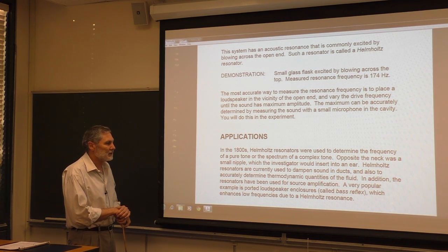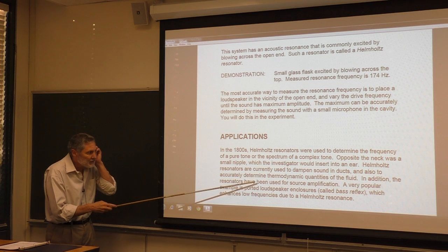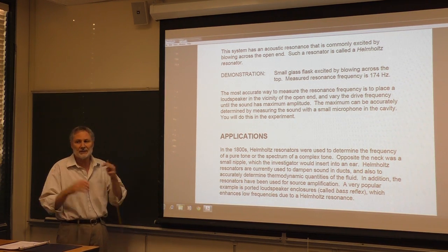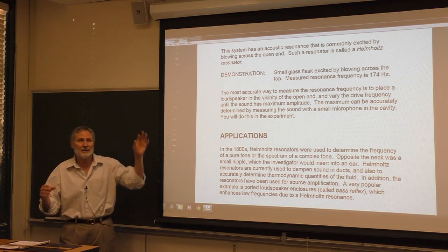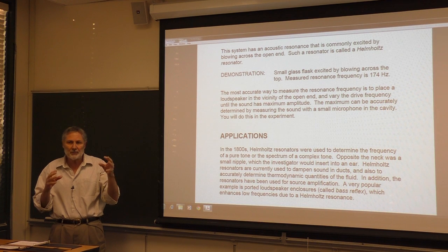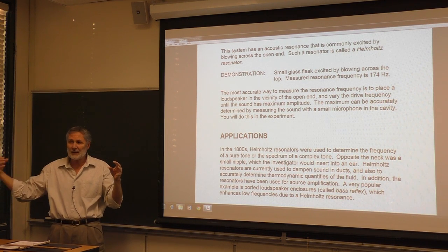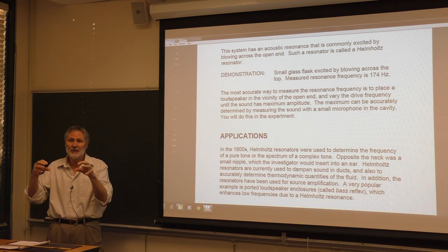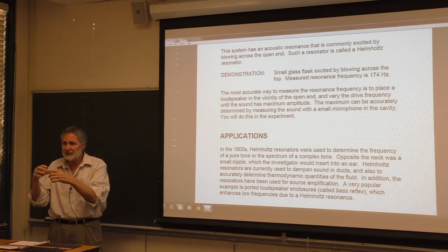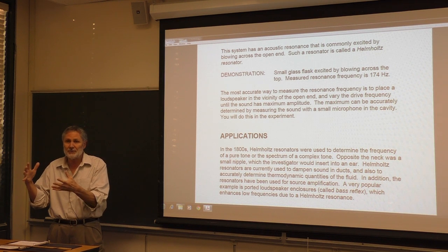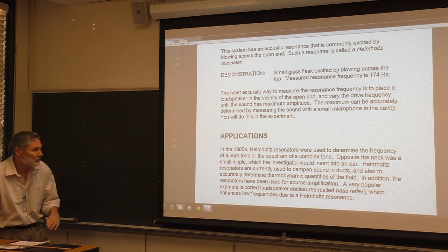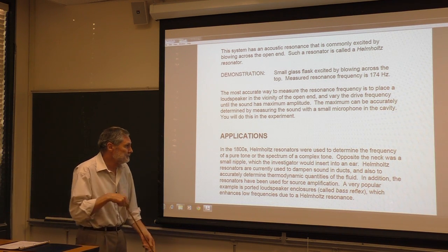They have a lot of current usage, as I'll explain to you right now. They're commonly used in ducts. If you've got unwanted sound, some kind of air conditioning or heating duct, and it's roughly a pure tone, you can tack on a Helmholtz resonator in the duct there and tune it to be approximately that frequency. And because of the resonance, it'll resonate. That energy has to come from somewhere. It comes from the sound wave. So you can dampen sound in ducts. It's very common.